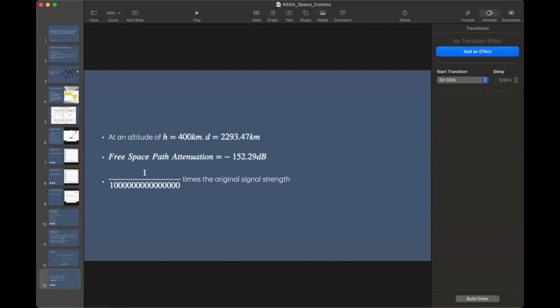Now, what we've got is a series of blocks. The first of them connects the software-defined radio head to the computer, which is here. We then do a little bit of stuff called rational resampling. It's changing the sampling rate. The initial sampling rate is 4 megahertz. So it's pretty fast.